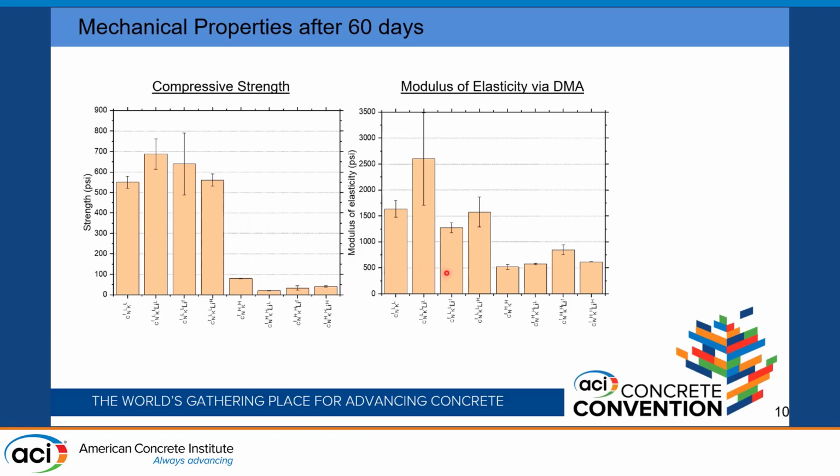The modulus of elasticity tests show that the lithium nitrate admixture is incapable of changing the modulus of elasticity, or might slightly increase it for the low alkali gels. And the setting time of the high alkali gels was also increased by the addition of lithium nitrate.